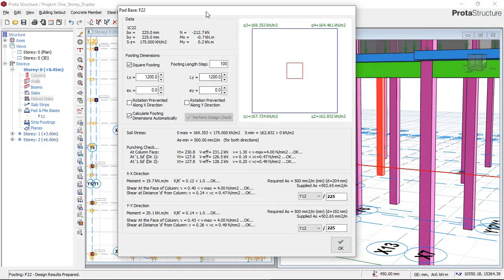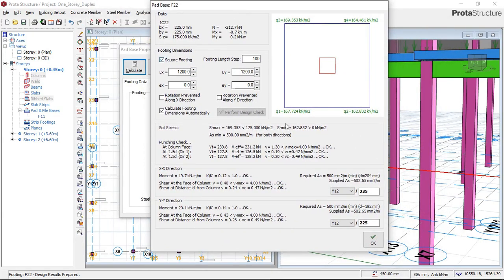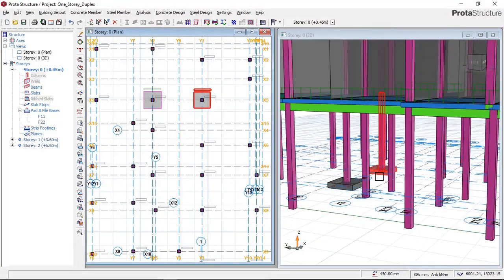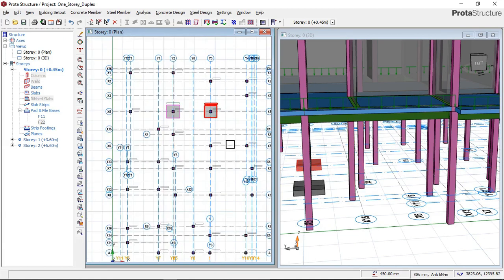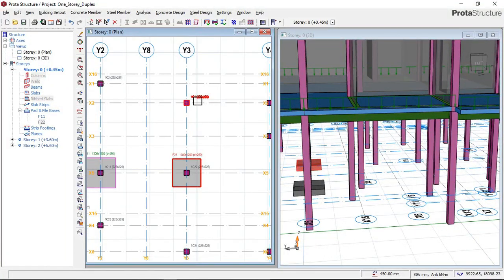The next thing to do, once you have done your first footing design, is to just be checking if this is okay, okay, and okay, and check if your spacing is more than 100 millimeter. You can now click on OK and then OK. You can see we have done our second footing, as you can see it here. So I will increase my pace on this so that I can save time on this video duration.